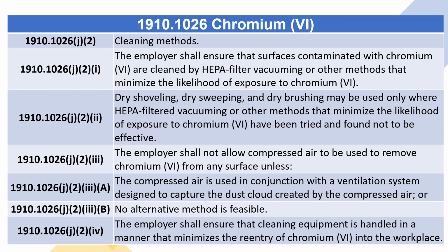1910.1026 (j)(2)(ii). Dry shoveling, dry sweeping, and dry brushing may be used only where HEPA filtered vacuuming or other methods that minimize the likelihood of exposure to chromium (VI) have been tried and found not to be effective.